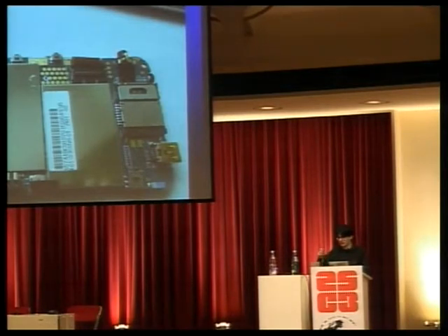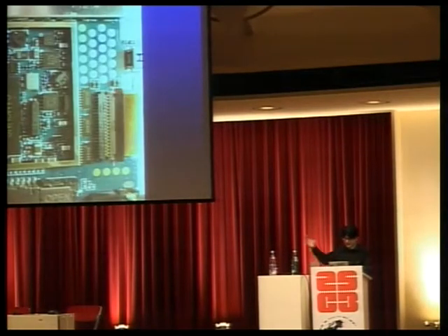So with a small screwdriver, maybe a scalpel, you can try to lift them. If they're soldered on, then you actually have to unsolder them or cut them open with the scalpel, which is what I did on one of my Motorola phones. So this is the uncovered application processor section. We can again see the Samsung system on a chip in the center. This one is the CPLD, which they use for various peripherals like keyboard scanning and so on.